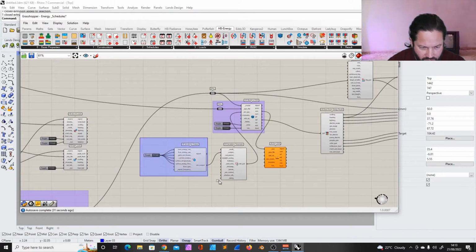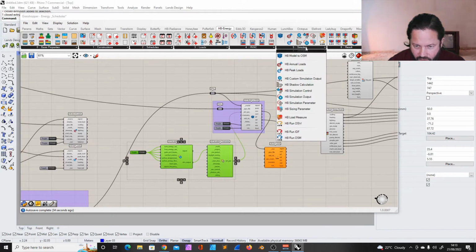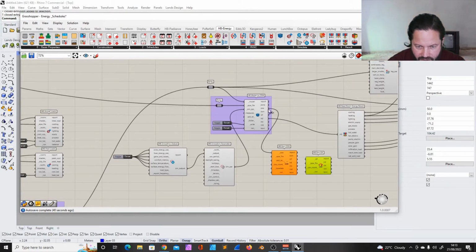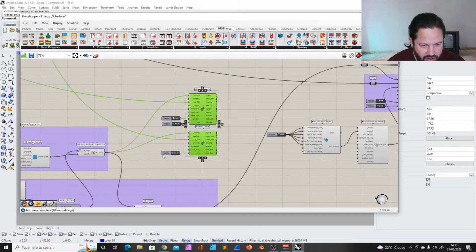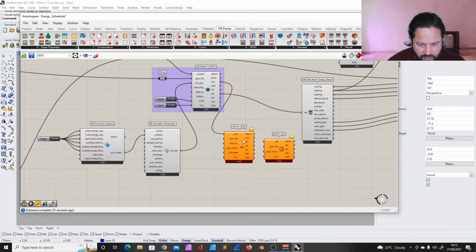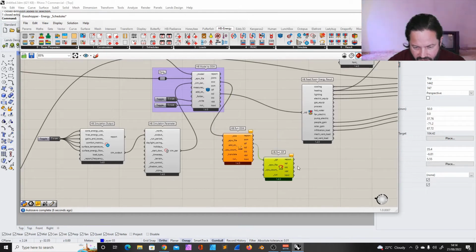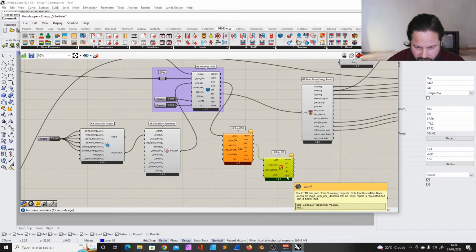And what's the point of all this is basically if I want to run all this here through EnergyPlus. As you know, EnergyPlus did not allow me to actually use the Honeybee model, but it seems like with this tool I can run the IDF file. Oh, sorry, here, IDF. I'm getting confused because here's an IDF output. Maybe that's already enough. But I could run this and I get an EnergyPlus report, for example, as an HTML file or as an SQL file, and so on.